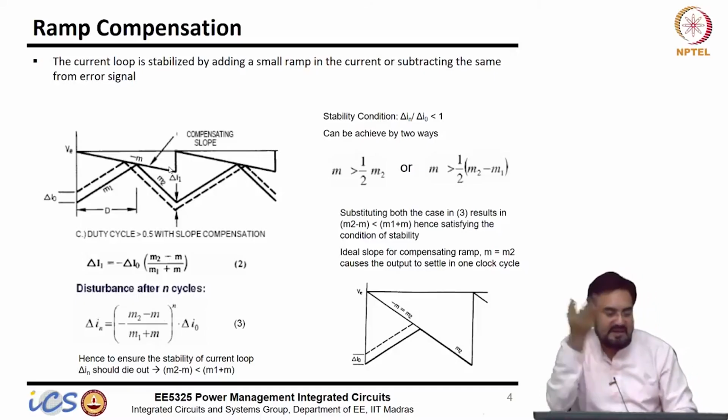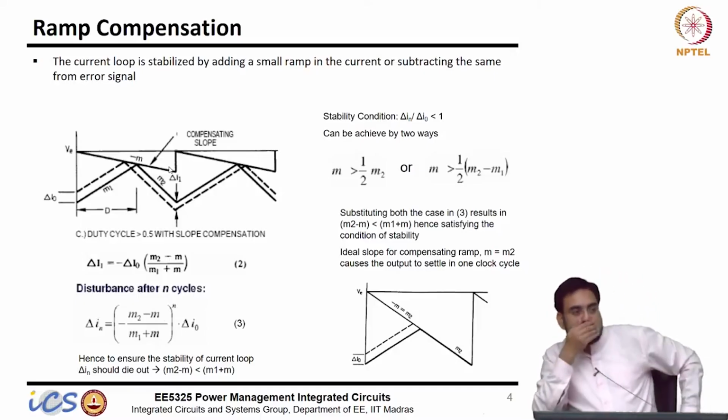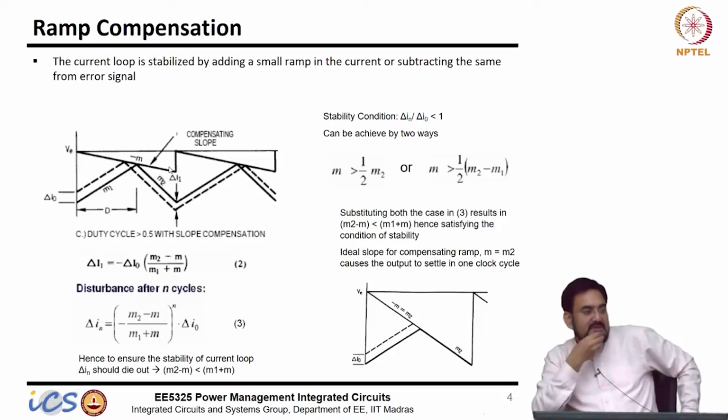Why? If I make it strong, what would happen? Peak current will reduce, but what will happen in that case? Average load current will change, so output won't be regulated. No, average, your control voltage can adjust that, you have outer feedback.